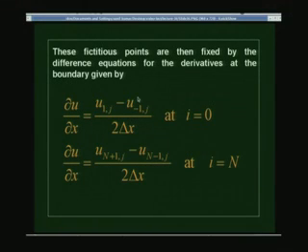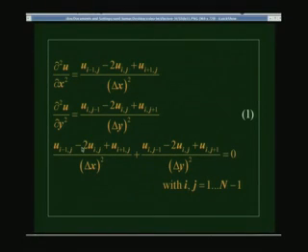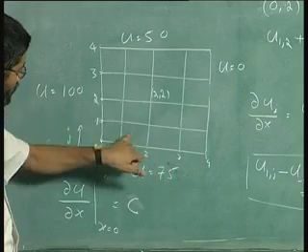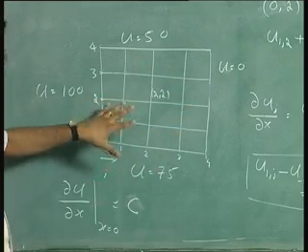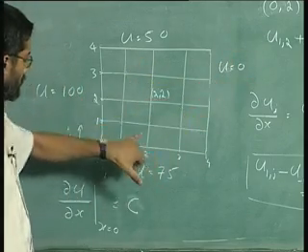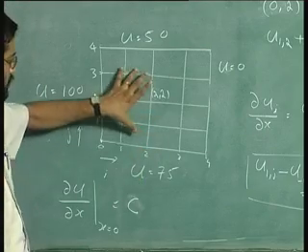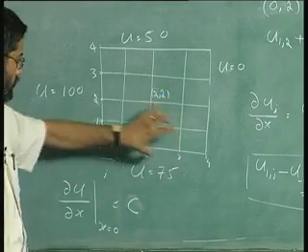So we see that you can either use boundary points themselves being specified. When you want to solve this equation, you could get the boundary points specified as boundary conditions, then you solve this equation only for a set of interior points, or else you have the derivatives specified. If the boundary values are specified, then you solve only for the interior points, and you could use relaxation methods or matrix methods to solve for the temperature inside.